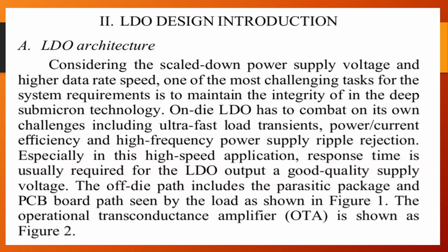LDO design introduction. Considering the scaled down power supply voltage and higher data rate speed, one of the most challenging tasks for the system requirements is to maintain power integrity in deep submicron technology. On-die LDO has to cope with its own challenges, including ultra fast load transient response, current efficiency, and high power supply ripple rejection. Especially in high-speed applications, fast response time is usually required for the LDO to output good quality supply voltage.